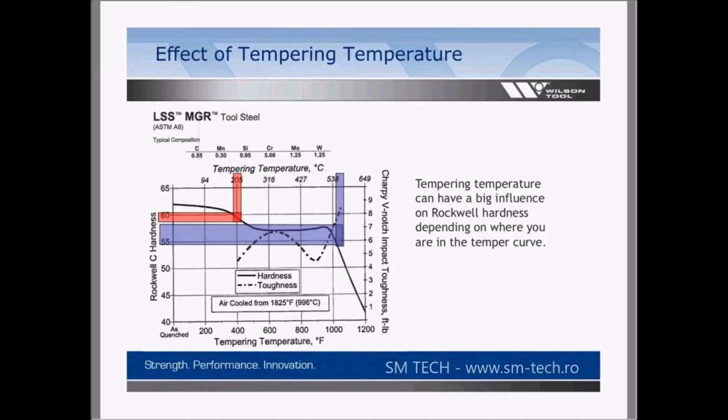So if you're not buying a finished product from someone, if you're sending out your material, make sure you're working with your heat treaters to get that optimal range and not batch it in with other materials that are widely different and have different draw times. That will cause some dramatic changes in your material. It may not show up because you're still going to see that Rockwell number, but the toughness might go away, or you might see the toughness but lose that Rockwell number. So you've got to keep an eye on that.